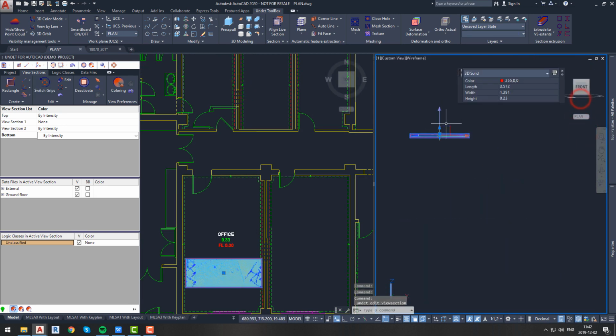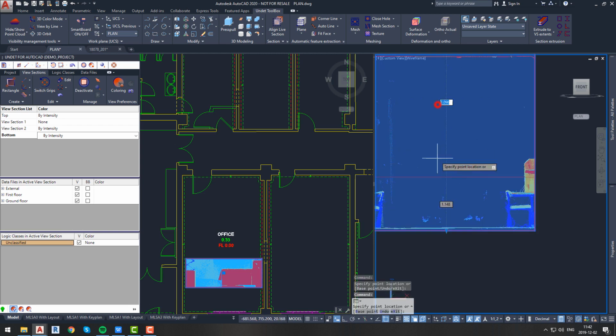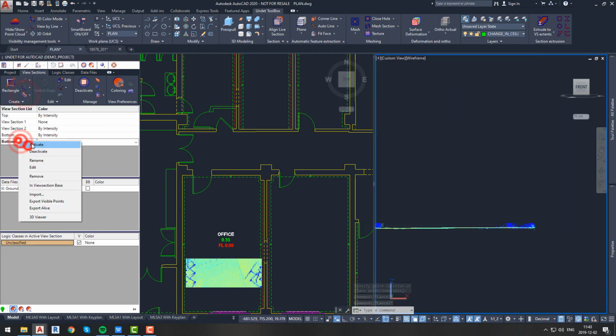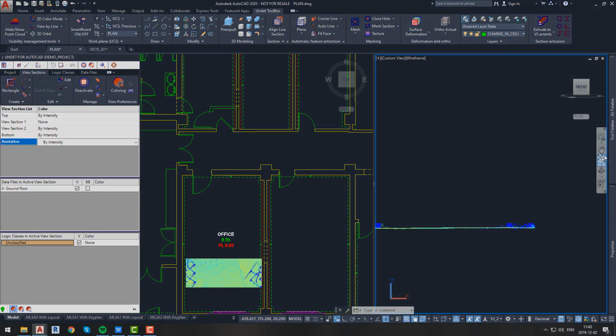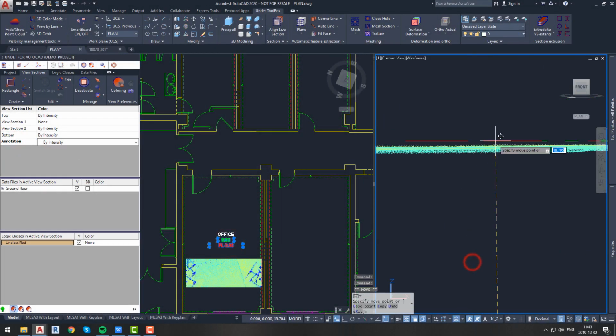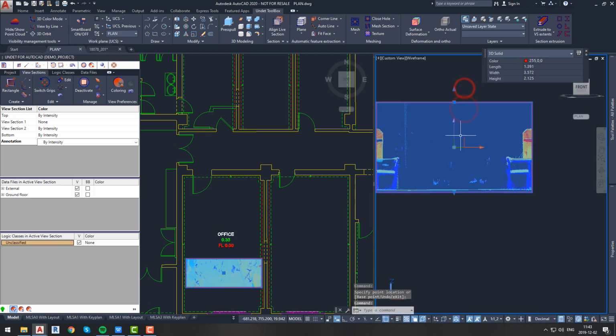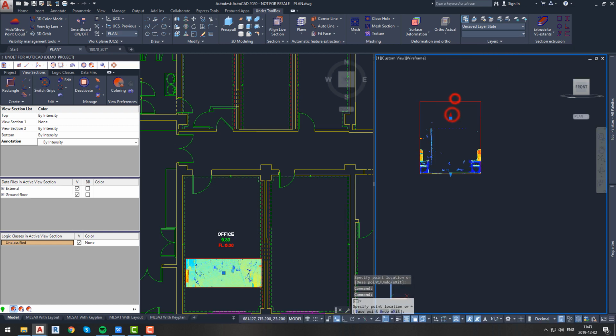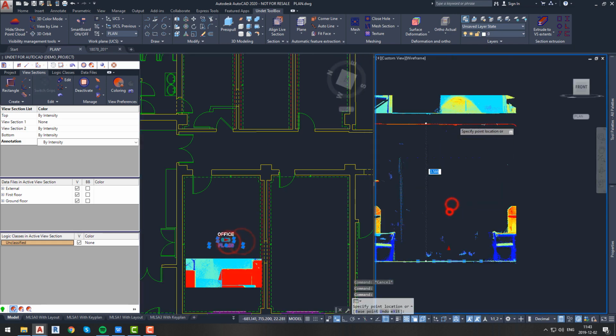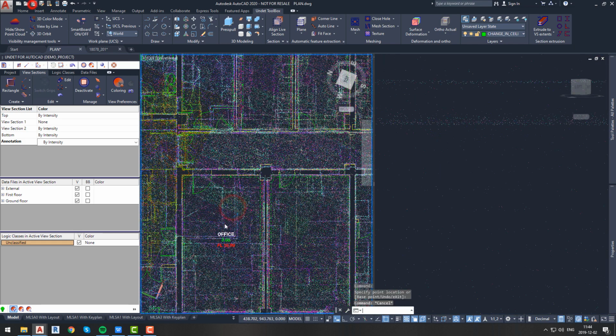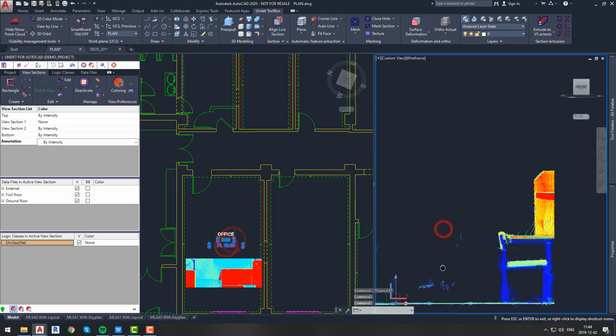Now we will have to create a view section throughout the whole volume of the room, since we want to see our floors and ceiling. After placing the room annotation, select it, and adjust its height so that it will be on the same level as our floor level. After that simply drag the arrow up or down to ceiling height, and now you have your room annotation. It is normal that the annotation value is the same. It will only change after you save your drawing.